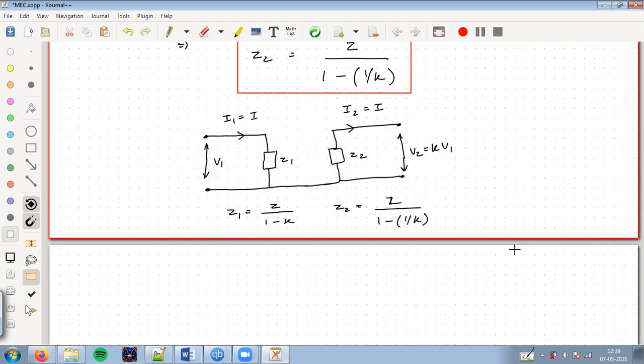The reason we need Miller's theorem is to separate my inputs and outputs. Under high frequency analysis of MOSFET, you have a capacitance which connects between gate and drain. That will show up in the small signal model, and I don't want it to complicate my analysis. So I replace that CGD with Z1 and Z2 to perform my analysis. Now it is easier. I can associate Z1 with the input side and Z2 with the output side of the circuit, so your inputs and outputs will be clearly separate.